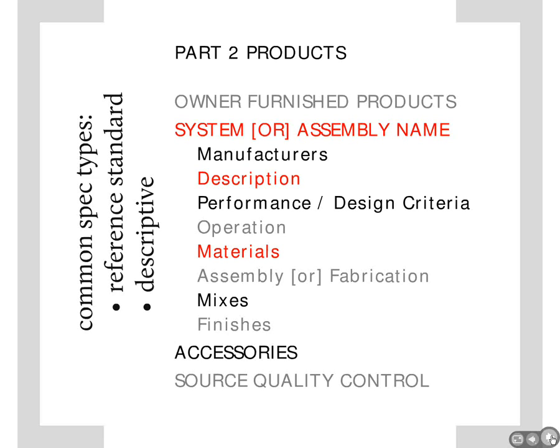Well, in general, you're going to have mock-ups to show how the bits and pieces go together, and those mock-ups would be specified, of course, in Part 1, and they are really necessary to demonstrate the coordination and the level of workmanship, because this category of products requires a little higher level of skill than the stuff that just comes out of a box and can be screwed to the framing or screwed to the wall or bolted to the floor.